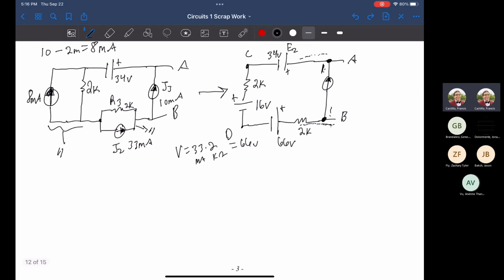So to finish off this, the equivalent circuit is just going to be straight in series, so 2K resistors in series, and then same thing with the voltages in series as well. So you just do the summation of it. If there are any conflicting orientations, do the difference of them. What I mean is specifically here. So voltage source there, and there.